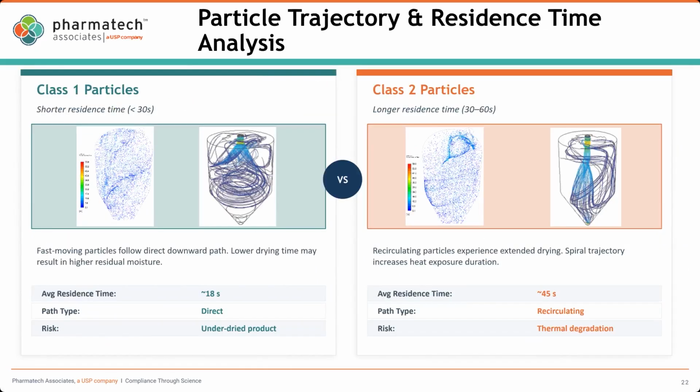After atomization, now we go to the chamber. This is the same chamber, same particles, but I'm separating them based on the D10 and D90. See, D10 has a longer residence time in the chamber. These are smaller particles, fluffier and lighter, and they recirculate inside the chamber, which you can see on the left side. And on the right side, this is D90: heavier particles, shorter residence time, and they fly out faster.